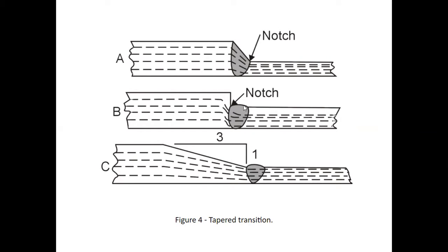This middle one, we can work this in 2 different ways. We can add additional weld if we have the ability to help taper this out a little bit, or we can simply grind this back on that 3-to-1 to help create that better effect with the weld.